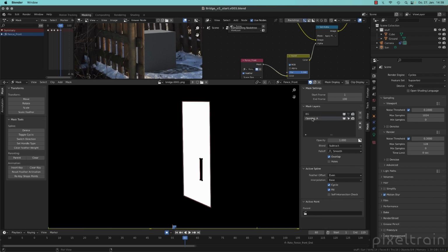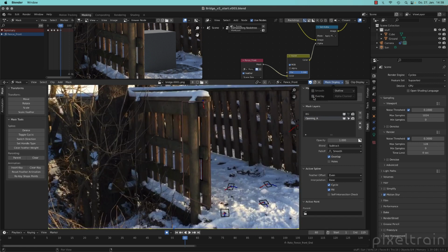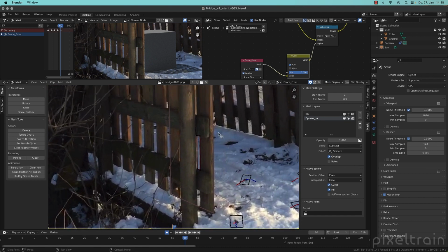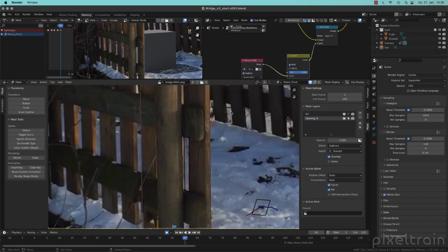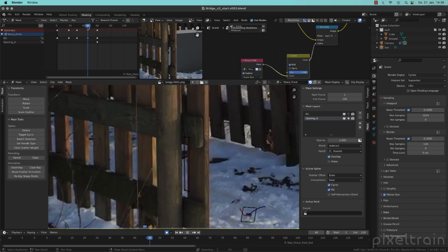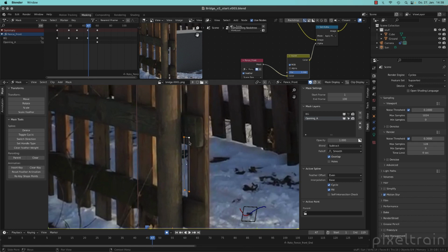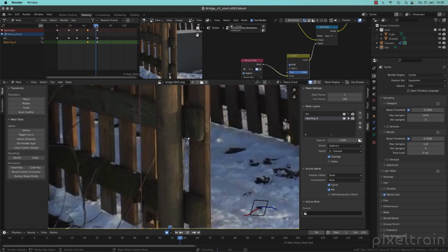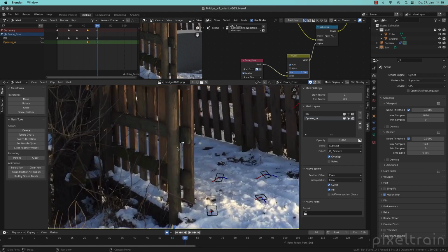What you now do is you go here to this opening here and do the same thing. This time we don't use here a tracker as a helper. So what I would do now is I go here. You can open that here. See, this is our first keyframe. So go some frames to the back. Select all these points here. Press the G key for grab. And now you can make here your adjustments. And that's the way we normally work here. This takes now its time, but I think the process now is clear.